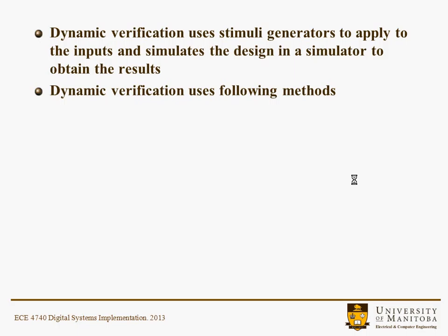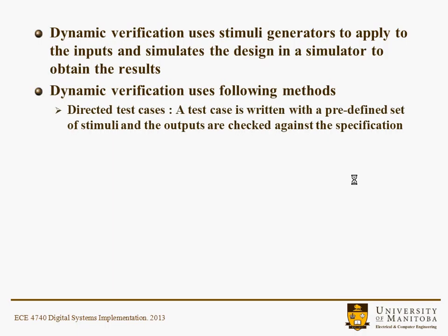You have stimuli generators, and they basically apply inputs and simulate the design in a simulator, and you obtain the results. So dynamic verification has a couple of different methods. One might be directed test cases. So these are ones that you think up. They're a predefined set of stimuli, and the outputs are then checked against the specification. Typically you're going to look at corner cases, average cases, but it's very unlikely you're going to generate a very large number of directed test cases.